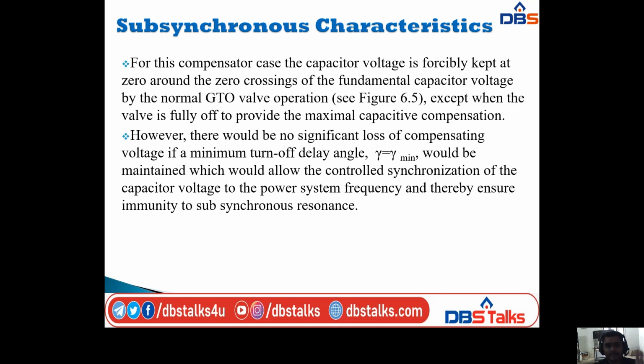For this compensator case, the capacitor voltage is forcibly kept at zero at the zero crossings of the fundamental capacitor voltage by the normal GTO valve operation, except when the valve is fully off to provide the maximal capacitor compensation.